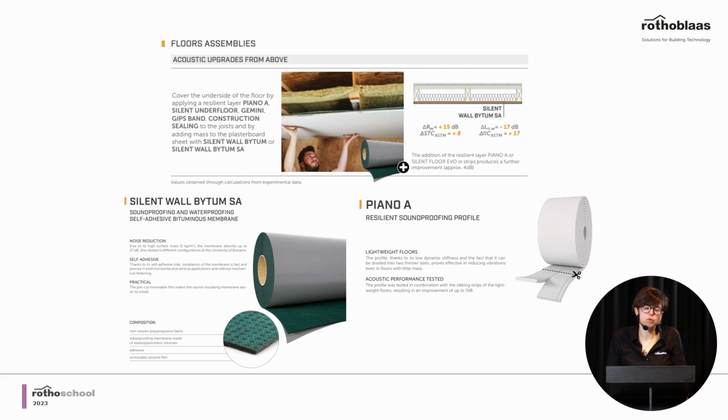When we work for the improvement of floors, generally we cannot work on both sides, because generally the owner is just the owner of one floor, either the upper one or the lower one. So, for example, if we can work only from below, what we can do is to construct a suspended ceiling, or